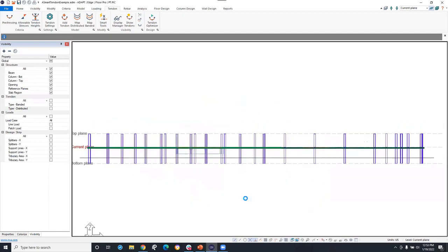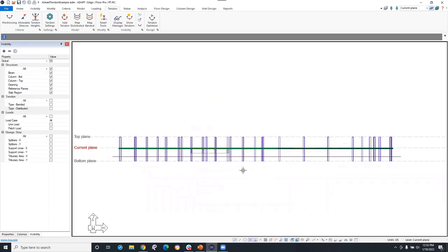So let's go ahead and go to the side. I'm sure if you're like me, there were plenty of times when I do a punching shear check, or I had a planted column that kept pestering me, thinking, hey, my brain keeps telling me it's supporting the slab, but hey, it actually isn't. I would always have to go in here, select these, and hide the columns. Now you have the option to hide top or bottom, and this option is also available for walls. Unfortunately, I don't have any walls in this model, so that's why it's not shown here. This is dynamic. It's only showing what is in your model.